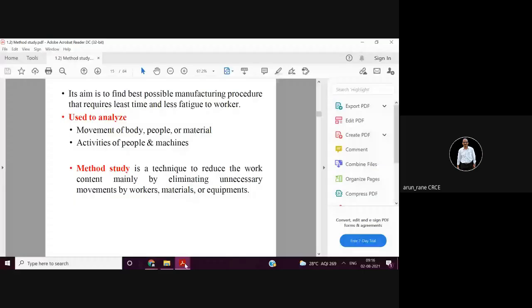So now the bottleneck is shifted to the lathe machine. You can take the decision whether to have one more lathe machine so that 3 minutes can be divided into 1.5 minutes, or just go ahead with the 3 minutes. That decision is taken by management depending upon the requirement of the output. If you are okay with a 3 minute cycle time, that is 60 divided by 3, 20 pieces in an hour, fine. You can go ahead with that 3 minutes.